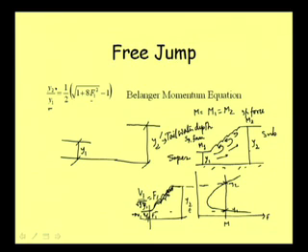Now if this tail water depth is equal to this sequent depth Y2 which corresponds to the Y1, that means for this Y1 there will be a corresponding Y2, and if this Y2 is equal to the actually existing tail water depth Y2 dash, then from this depth directly the jump will occur to this point, and this sort of jump is called a free jump.